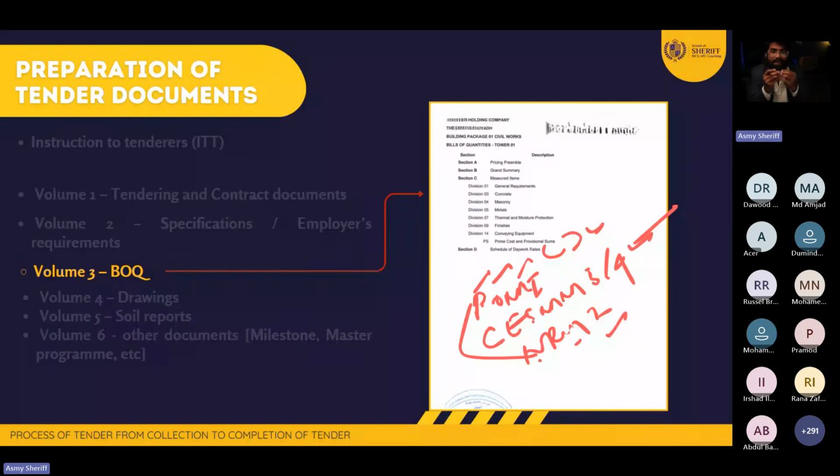Using these documents is standard. You can find them in the market, or in PDF form. These documents will guide you on how to prepare a BOQ. It's very simple. Find one BOQ format and open it. They will tell you that if you are going to measure concrete, all the area should be measured. And if you identify any void or small gap of less than 1 square meter, avoid that. Other areas, measure all of them. And that should be priced in cubic meter.